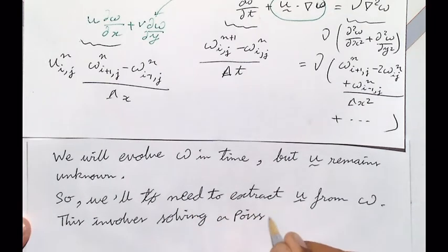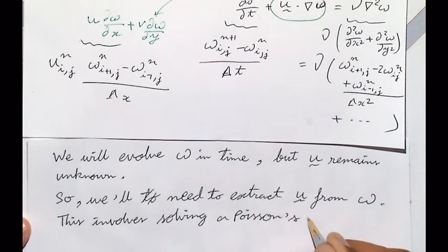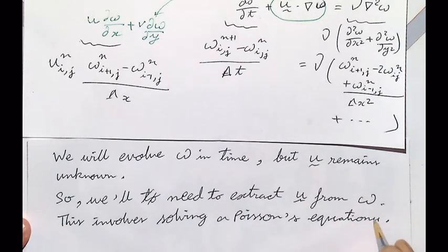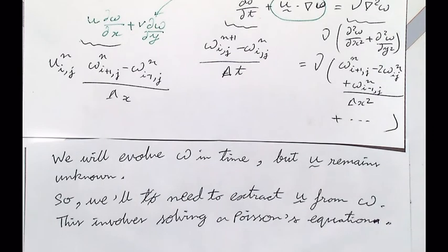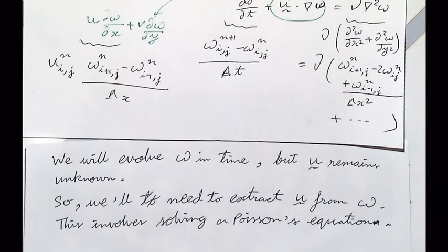So we're back to paying in terms of computational cost. So again, there's no free lunch. You had 90% of computation in the pressure Poisson equation. Now that will happen in the velocity Poisson equation. Okay? And to derive this, it's a very simple relation.